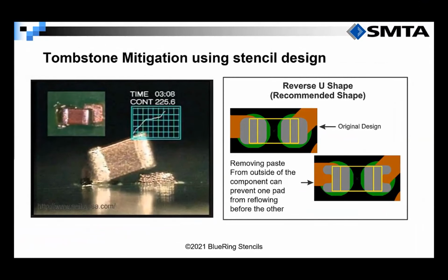In the case of very large pads where there is a lot of exposed solder beyond the part leads, for example, an 0402 placed on an 0603 pad set, more of the aperture may need to be removed from the outside to create a larger area of copper with no solder paste present. In some cases, I've removed 1/3 of the outside of the aperture when addressing tombstones.